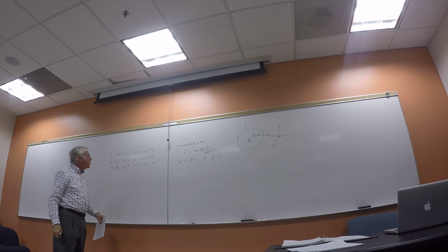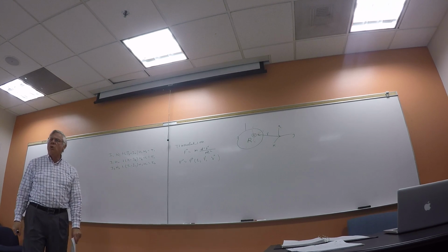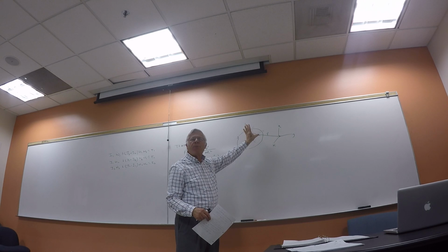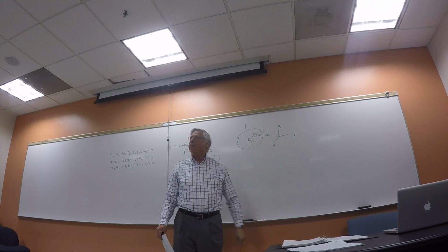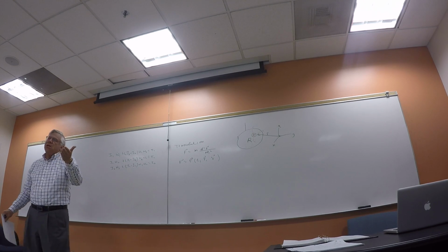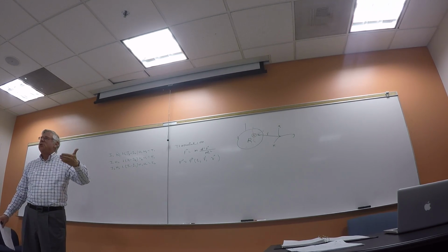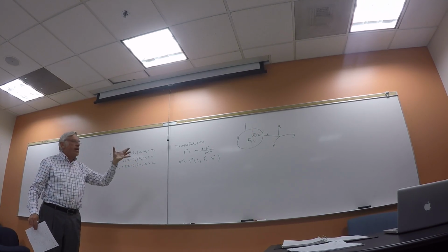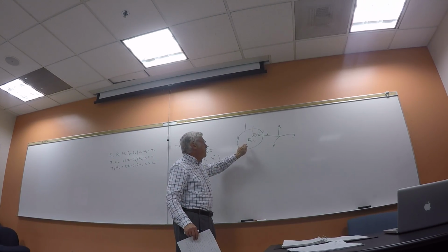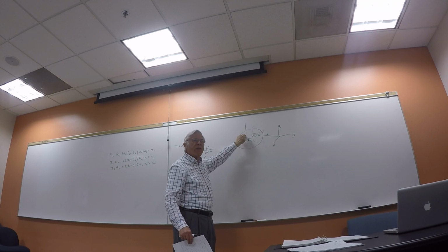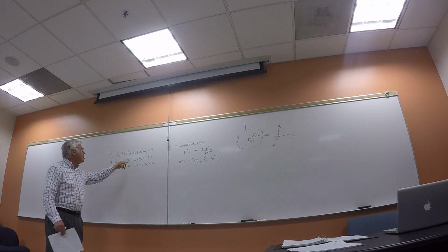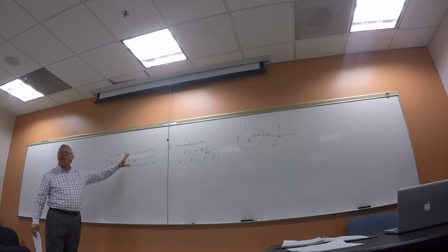Okay, what are all these symbols? Omega is a vector, has components omega 1, omega 2, omega 3. Those are the components of the angular velocity of this body in the body frame. Okay? I1, I2, I3 are the principal moments of inertia. Basically, what they tell you is how the mass is distributed, what a moment of inertia is, right? Clearly, the rotational dynamics depends upon how the mass is distributed. You know, is there a heavy payload over here? Is there some antenna over here, right? That'll change the inertia matrix, okay? But the numbers I1, I2, I3 are constant, at least for a rigid body, okay?